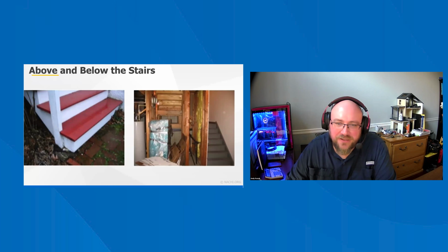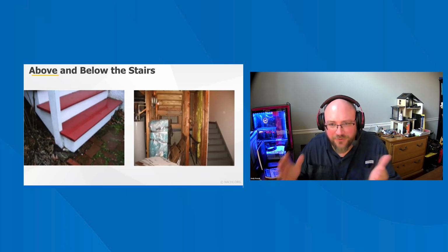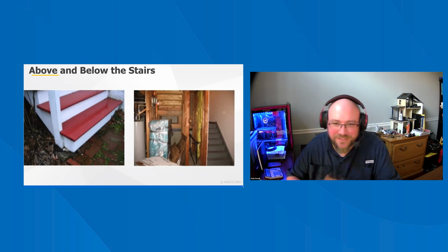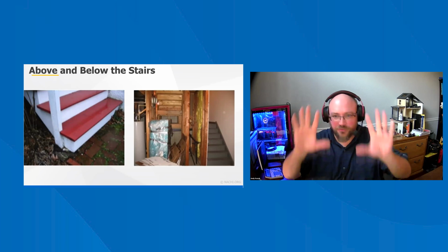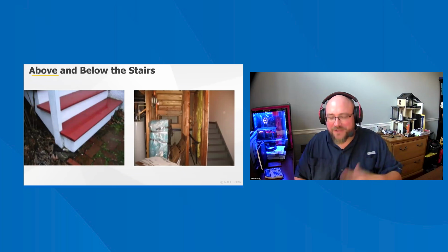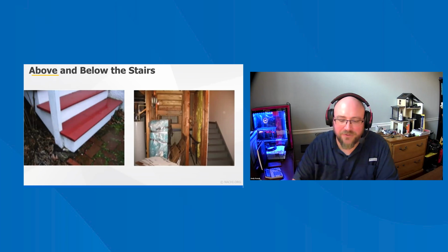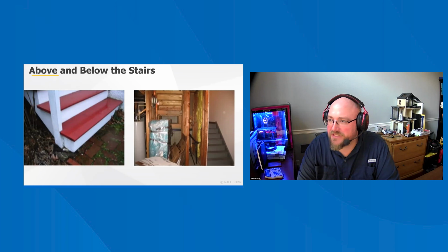I find this a lot, especially on crawl spaces or unfinished basements where maybe a set of stairs was added later. You'll see low headroom, and as long as you call it out, you identify it, you tell the homeowner, hey, this is lower than 6 feet 8 inches, and let them figure out if they want to modify it or if they just want to put a cut-in-half pool noodle on the header above there, which is pretty common, or just put up a watch-your-head sticker. That's a lot of times what I'll see when the headroom is lower than expected.